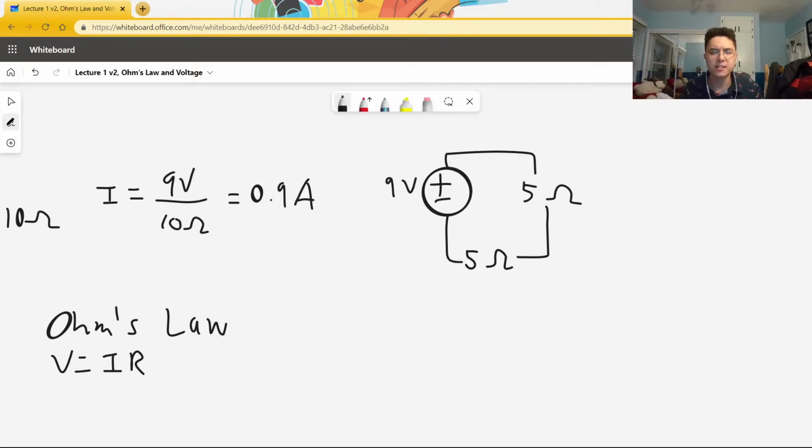In circuit analysis, it is a useful mathematical tool to talk about something called a voltage drop. A voltage drop is, in some sense, how much of the voltage of an electron, of a charged particle, gets used up when you travel over something like a resistor. Now let us say there are 2 resistors in this circuit. We know the particles don't slow down upon going through a resistor. In fact, the current through this entire circuit is the same at all points in the circuit. But energy is being used by the resistor. The particles bouncing around are being converted into heat.